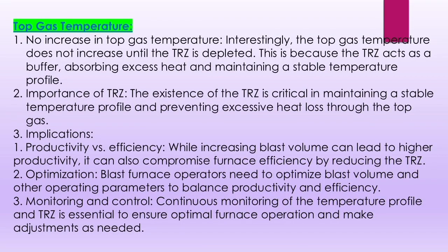Top gas temperature. 1. No increase in top gas temperature. Interestingly, the top gas temperature does not increase until the TRZ is depleted. This is because the TRZ acts as a buffer, absorbing excess heat and maintaining a stable temperature profile. 2. Importance of TRZ. The existence of the TRZ is critical in maintaining a stable temperature profile and preventing excessive heat loss through the top gas.